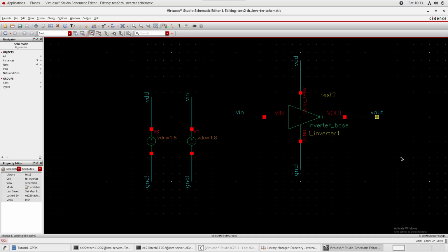You will connect an oscilloscope probe, right? That oscilloscope probe will have huge amounts of resistance. It will have some cap, all this. Right now, this Vout doesn't have anything. And that's why Cadence is saying, are you sure this is a floating net? There is probably something connected to it.